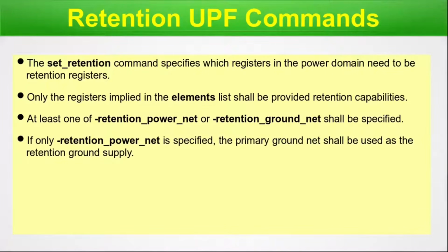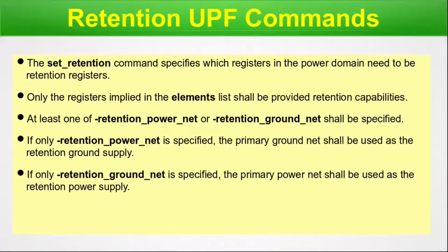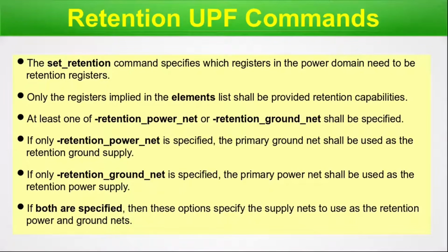If only the retention power net is specified, the primary ground net shall be used as the retention ground supply. And if only the retention ground net is specified, the primary power net shall be used as the retention power supply. If both are specified, then these options specify the supply nets to use as retention power and ground nets.